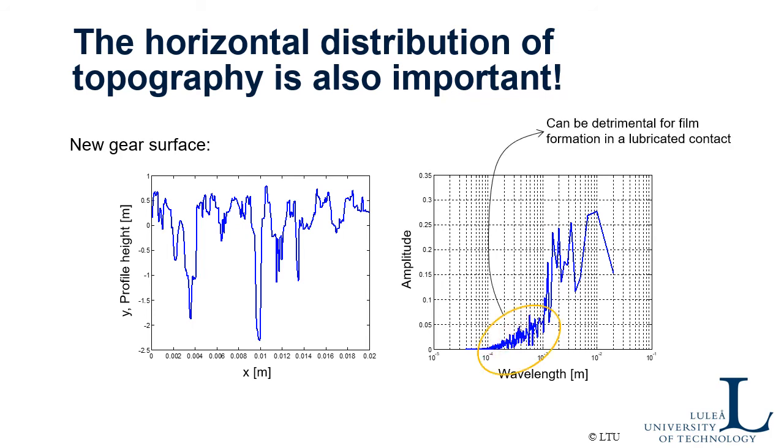Even if the amplitude of the short wavelengths is much smaller than for the long waves, it may be that those are penetrating the oil film and creating some wear or scuffing problems, because those are more easily deformed elastically than these, because these are sharper.